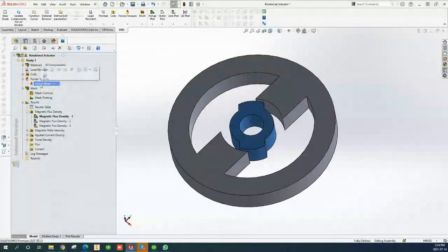Because I have virtual work, I want to compute the torque. And you know the torque is the most difficult quantity to compute. Usually we recommend that you do a very fine mesh. If you want to compute the torque, please do a very fine mesh on the surface of that body, because the torque is very sensitive to the mesh.